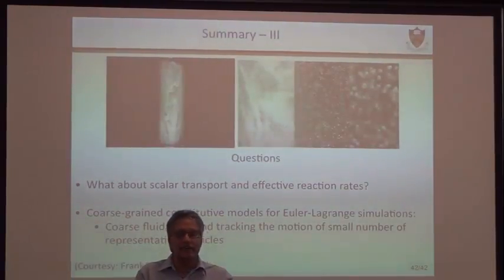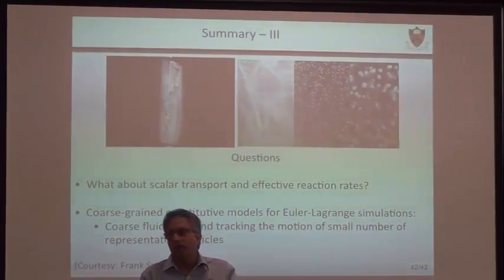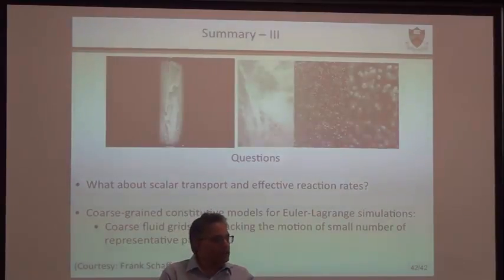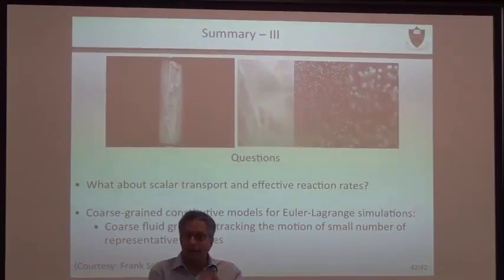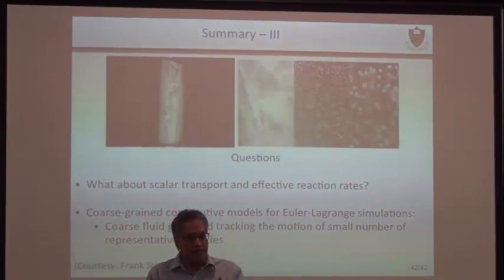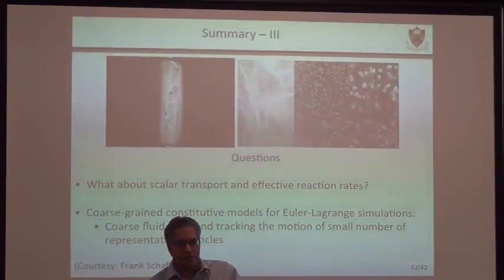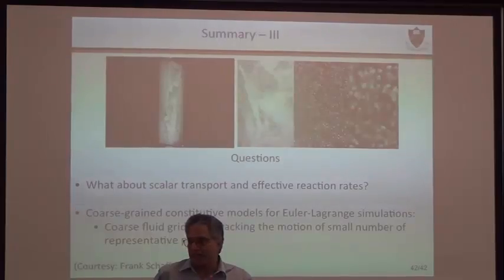The particles can have some cohesive force of attraction. Sometimes liquid bridges form between a few particles, causing agglomeration. You can have particles rubbing against surfaces and picking up charges, so you get electrostatic interaction between particles. In polymerization reactors, that is the biggest concern they have.